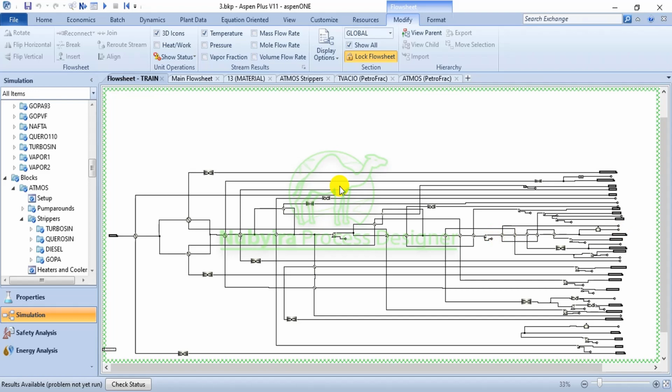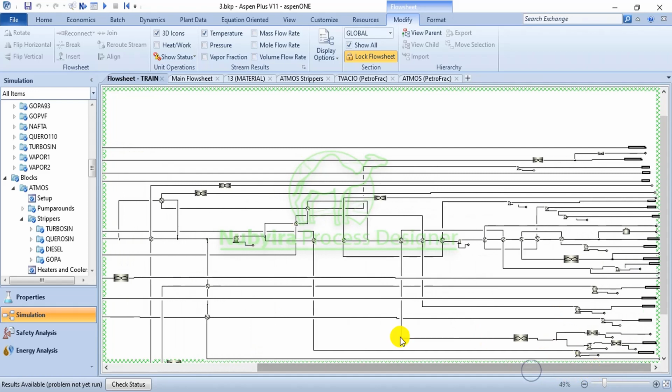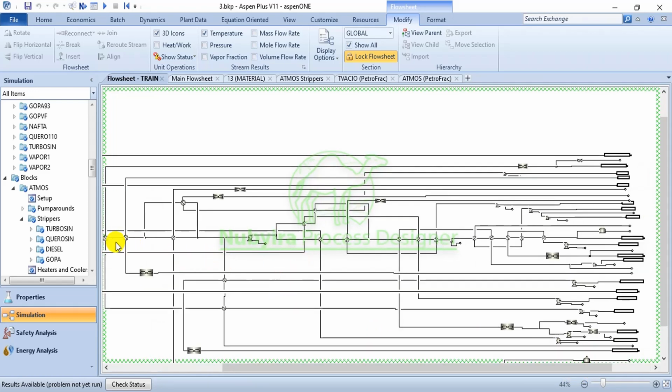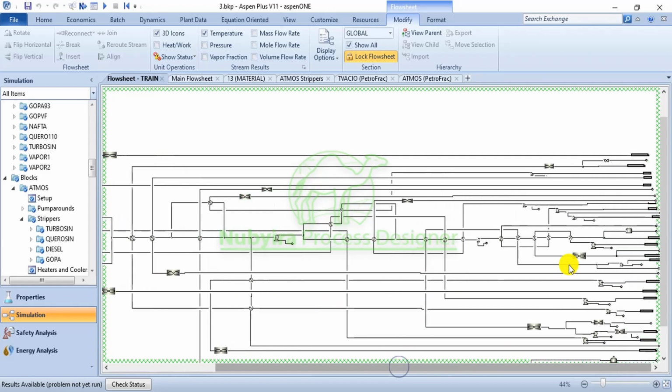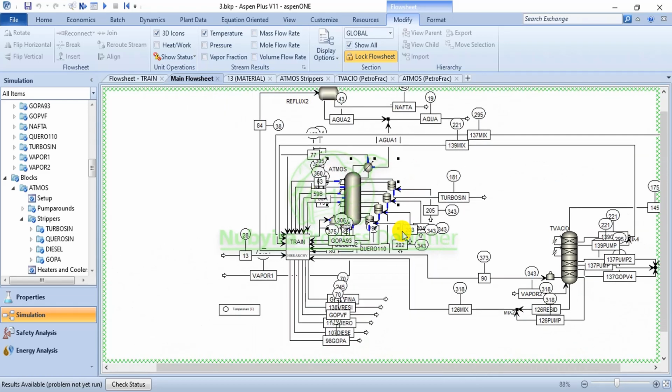So, in order to do that, although I've done that before, I have specified the temperature of the heat exchanger network and connected it in such a way, because what I'm doing currently is just a rating design, rating optimization of a process. I use a refinery process for it, and so there are some specifications for the heat exchanger. So I will be adjusting those specifications in order to increase the outlet temperature of the crude from the heat exchanger train.